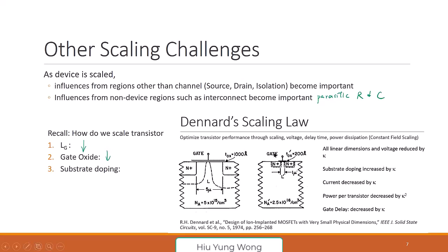Okay. How about for substrate doping? Do you want to increase or decrease? Increase. Okay. Increase here, actually, you find that is consistent with one thing. When ND increases, it means WD or WM decreases, because WM is proportional to square root of 1 over QNA or QND, right? So this is consistent, right? So they use different theory, eventually they all come to the same place, right?